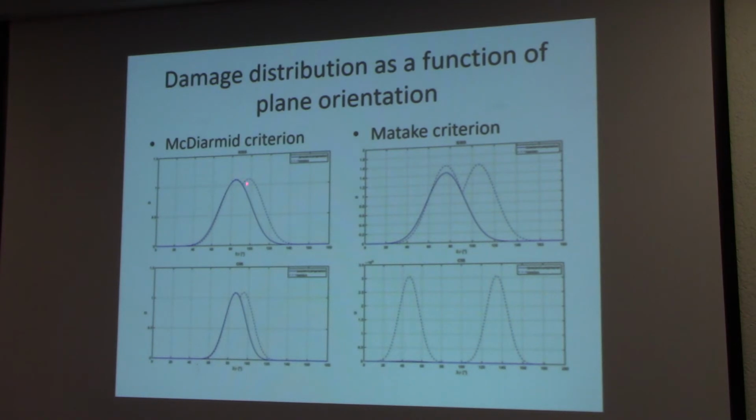And the difference between these 2 points is very sensitive to material parameters and the shape of loading signals, which we will see later. Okay, this is the case of C55 steel, and you can see clearly that the inconsistency, the very strange ratio between the fatigue limit in pure torsion and pure tension loading, leads to very obscure results, and the criteria doesn't work for this kind of steel. Okay, so I won't use them anymore.